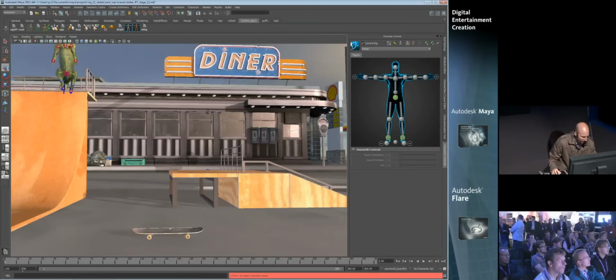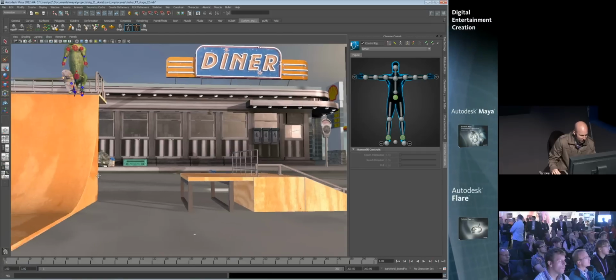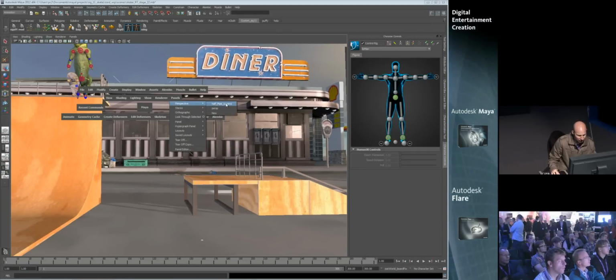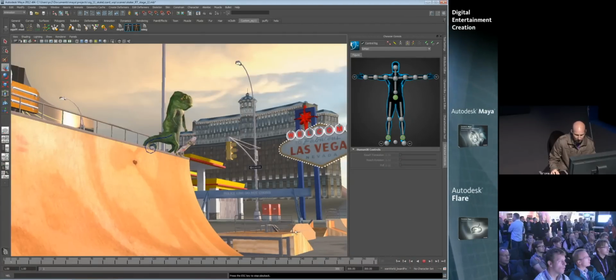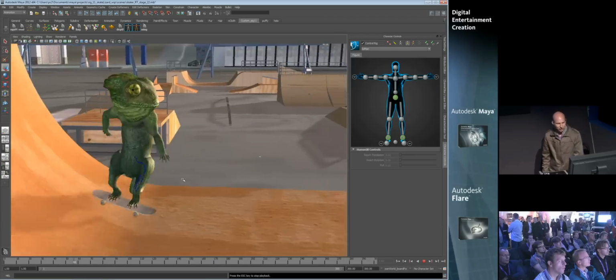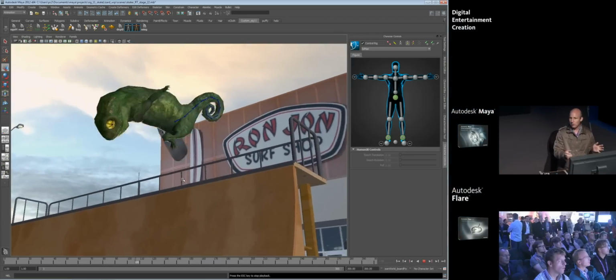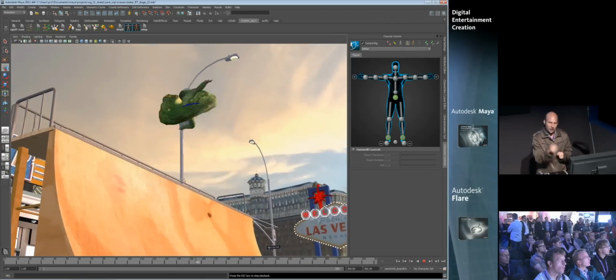And now you can see if we just start at frame 1, which we're at, I can jump over to this camera here, this half pipe cam, and clean up the display a little bit. We don't need to see that stuff. We play this back. What we have inside of Maya now is that same movement. So all the work in Motion Builder, single-click workflow right into Maya.